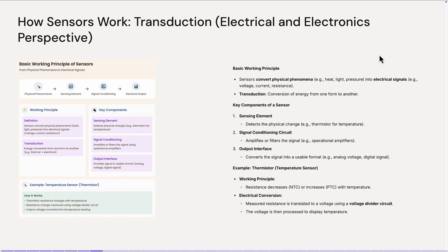Some other sensors can convert heat into electricity. So at the end, what every embedded device is going to measure is maybe just a voltage output, and this voltage output is going to be converted into a digital signal. If you remember the ADC, what does it do? Analog to digital converter. It takes an analog signal, which is a voltage level, and converts it into a number between, for example, 0 and 1024, if it is over 10 bits; the resolution can vary. This is what makes the value that we receive from the sensors, from which we can infer the value of the physical phenomenon.